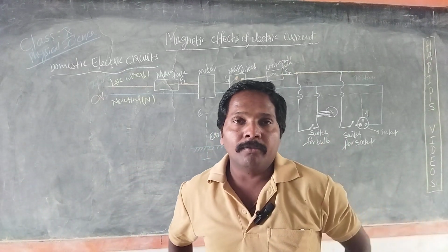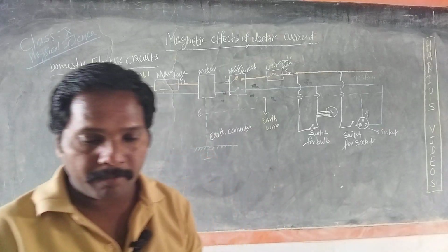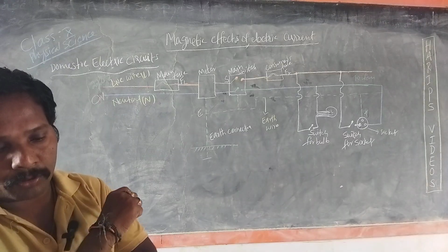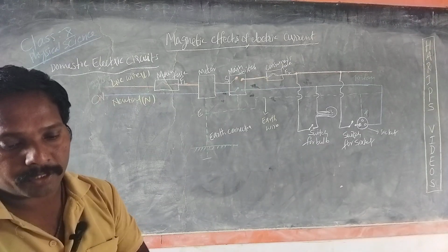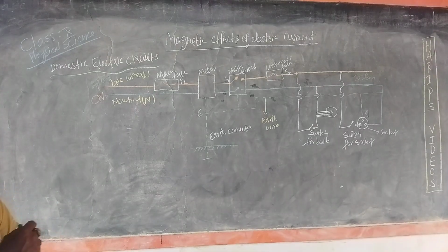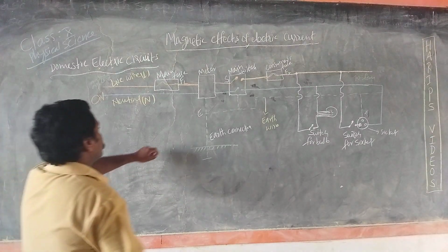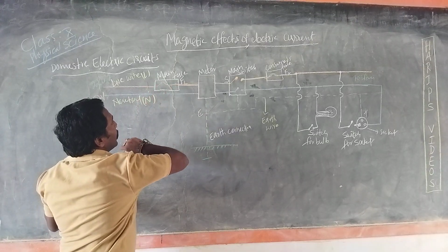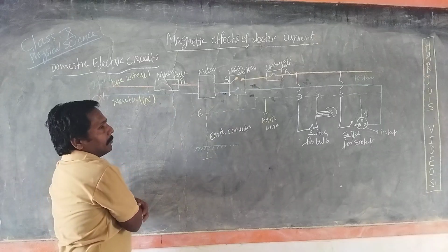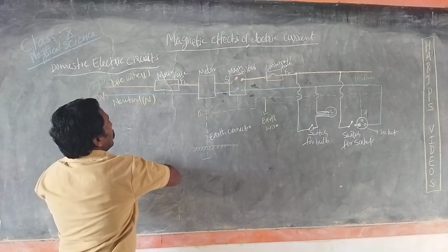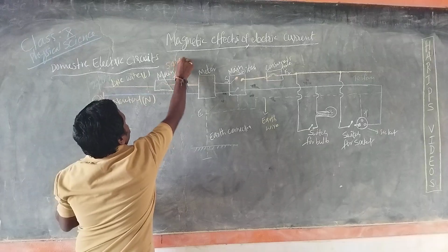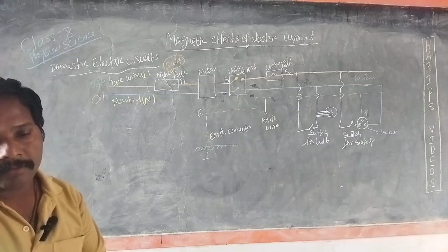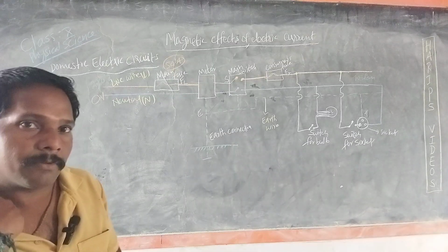The two insulated wires L and N coming from the electric pole enter a box fitted over the house. In this box, a main fuse is put in the live wire. This fuse has a high rating of 50 amperes. See, the live wire is connected to the main fuse in the box. Its range is 50 amperes, meaning it is able to hold up to 50 amperes of current.